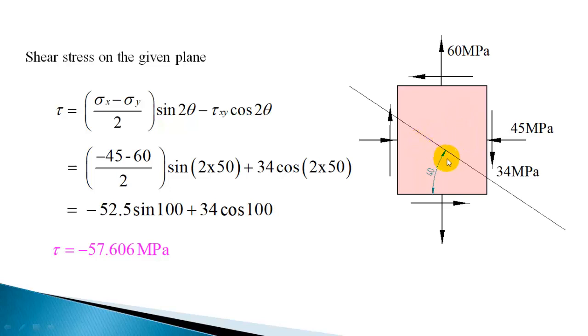So this shear stress will be downward here, and this part will be exerting an equal amount of shear force on this, so that it will be acting upward. So shear stresses will be acting downward from here and upward from here. So that is the minus sign. So even if the direction changes, the magnitude of the shear force is significant there.